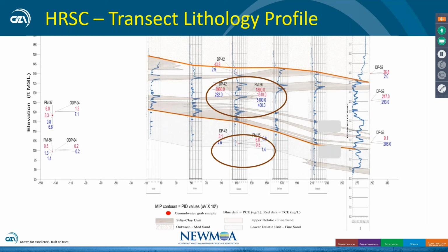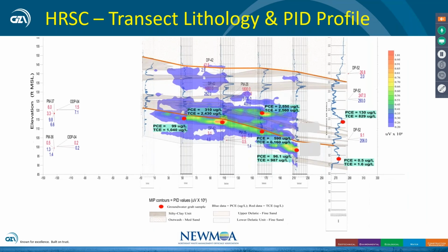That sounds really good. We were going to go out and we did our studies and our geochemistry, and we looked at how much oxidant we needed and all those fun things until we went out and did some high resolution site characterization. Again, a cartoon only, but these are PID values from the high resolution. What you see is that we have a lower boundary condition that all of us use as boundary conditions. And what we found was up to almost 6.5 parts per million of TCE directly below the clay boundary. Nothing that we would have expected.